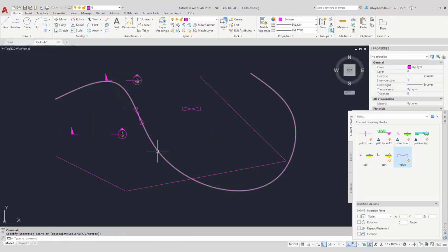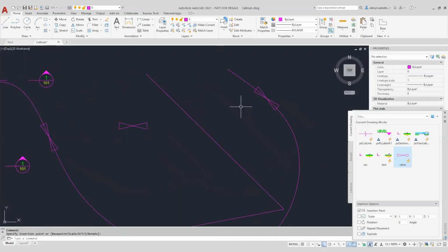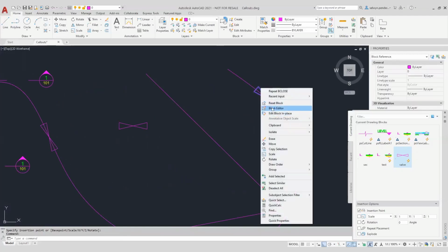Okay. See, having that one single parameter on any block, I have to say, is extremely useful, just to save the time of trying to rotate something, particularly when you're trying to rotate to a curved object and get that instantaneous curve point or UCS point. That's an extremely good one just to nibble on to the end of a block.